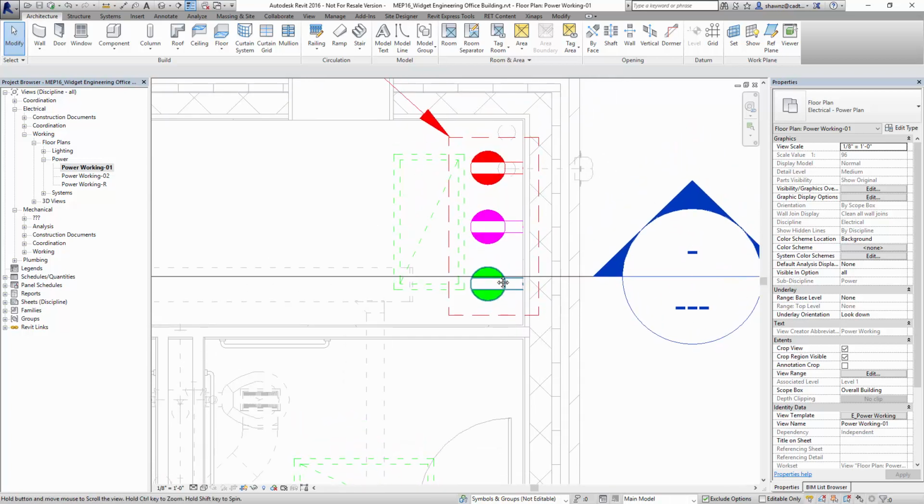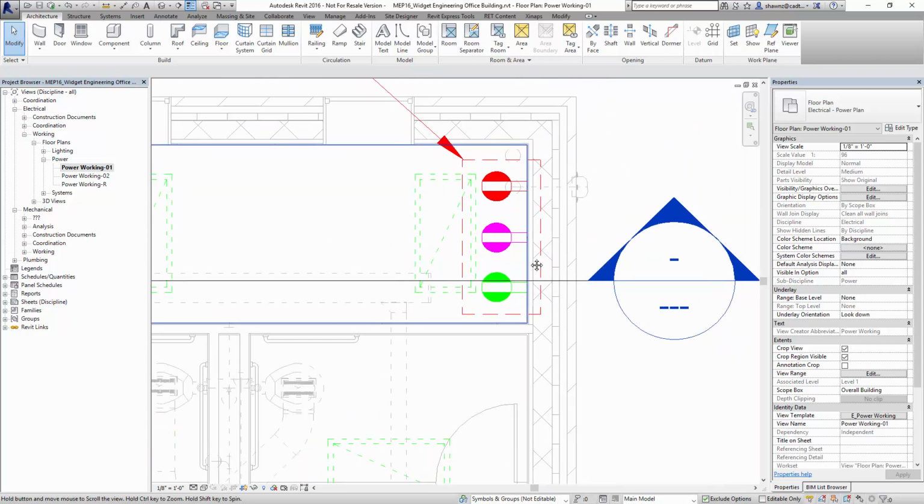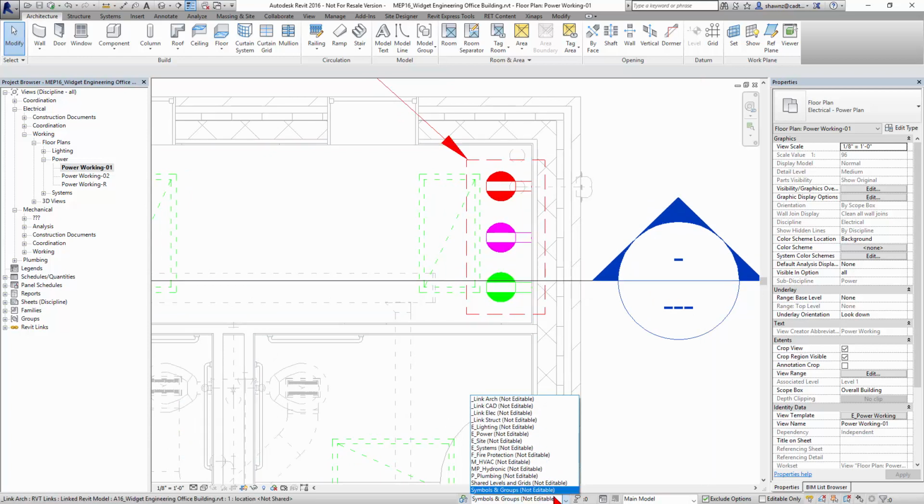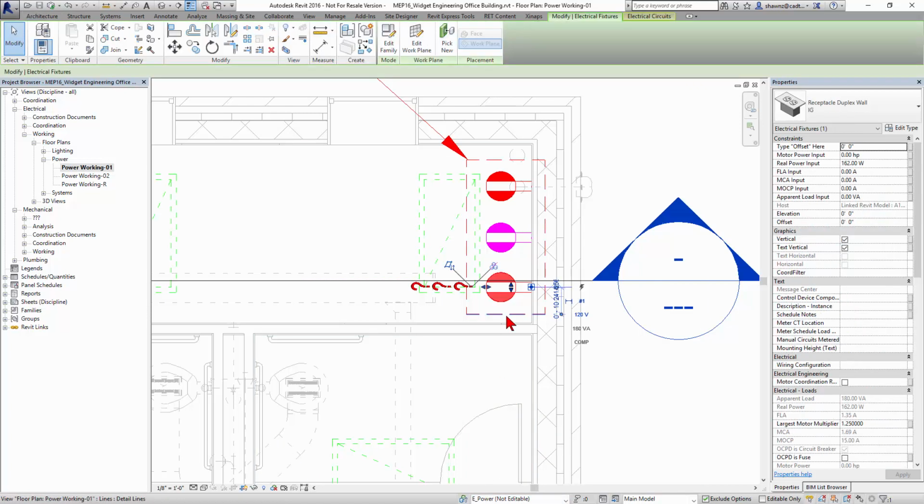Now, if you can't see these colors, or you don't like them, you can change our filters for the color schemes, but you know that you have those different colors available, so you can go through and work with this content. Now, let me give you an example here. I'm going to make sure I've got the right work set available. Let me go change to ePower, so I'm on the right work set. I'm going to take this component in Revit, and it's already circuited. I don't know what circuit it's on, but it's on some circuit and it's associated to a panel.